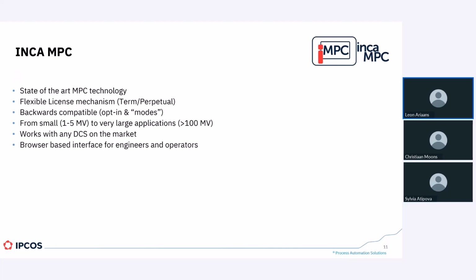Operators can also use that browser-based interface, and there are companies where the browser is the main user interface for INCA MPC. Other customers prefer to have screens on the DCS that allow the operators to operate INCA MPC, and you don't have to choose, one doesn't exclude the other. The main advantage of using the browser-based interface as the operator interface is you don't have to do anything additionally. It comes with the package, and if you make any changes to the configuration, if you add an MV or a CV, the interface follows along automatically. No further work is needed there.